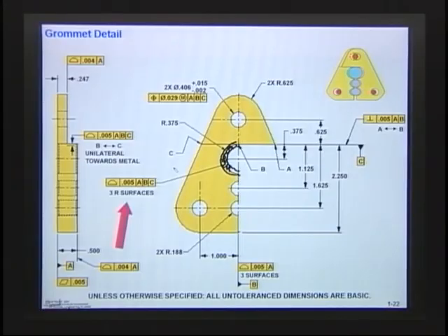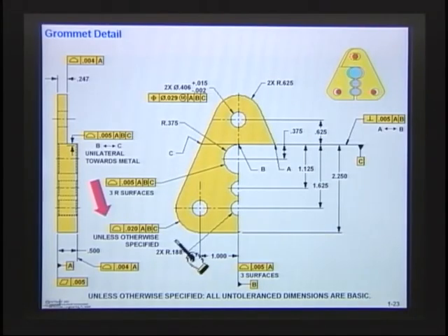All right, let's take a look at another one. You're noticing how nice this profile is. Everything else, I guess I'm getting tired, there's nothing else to do here. You notice as we get further along, down here I say, unless otherwise specified, everything else is profiled within 20 thousandths. So I have a large profile tolerance, and everything is covered with it. That's my largest tolerance, so that's what this does: profile within 20.